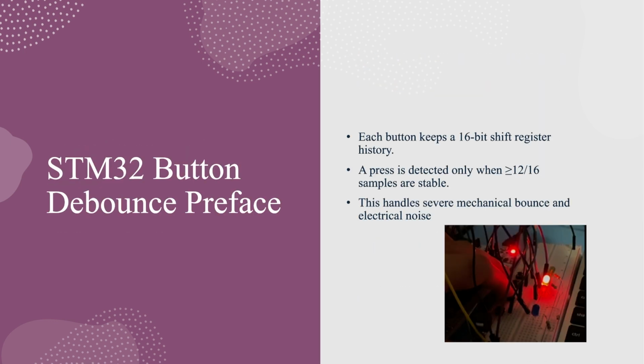Our STM32 button debounce. Each button keeps a 16-bit shift register history. When we press the button, only when 12 out of 16 samples are stable will there be an input, else it just ignores it. This handles mechanical bounce and electrical noise from the button itself.